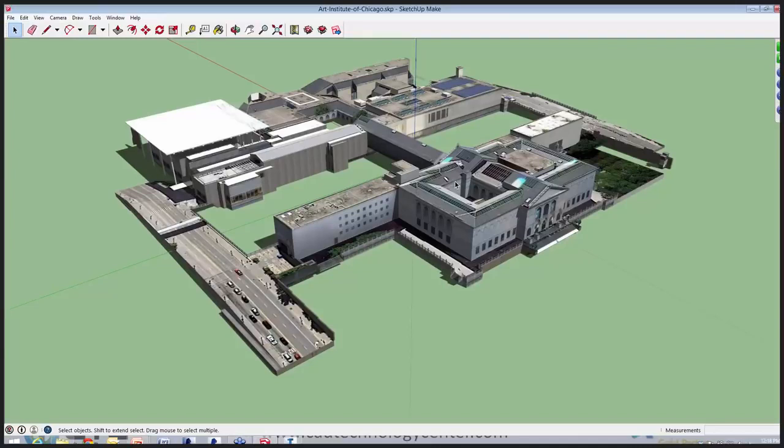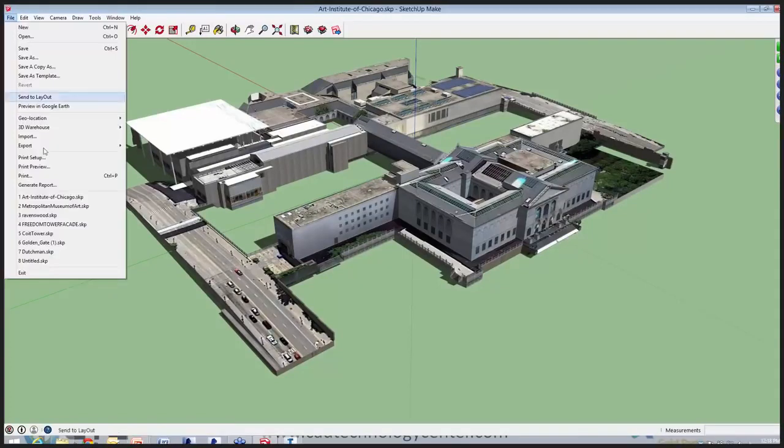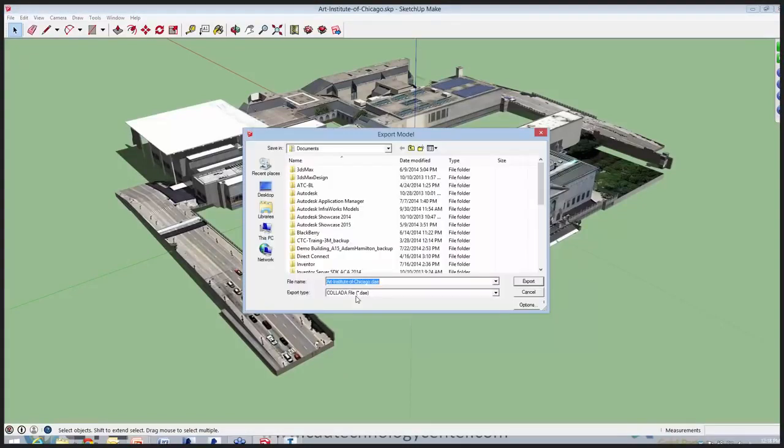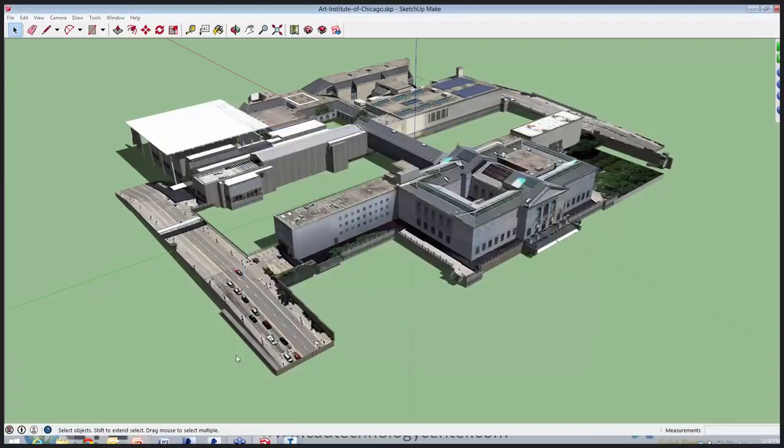We've found that out due to size, due to amount of faces, and so what we've found is as long as you bring it into SketchUp, which is a free download, free application, that you can export out the 3D model to say a Collada file, DAE format, and it works very well inside the Infraworks environment.